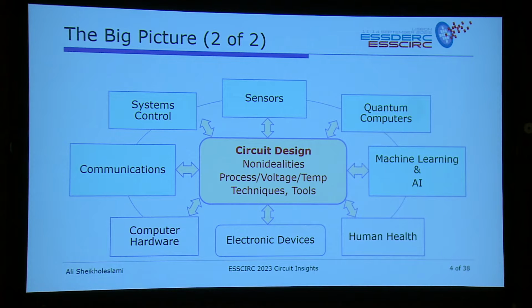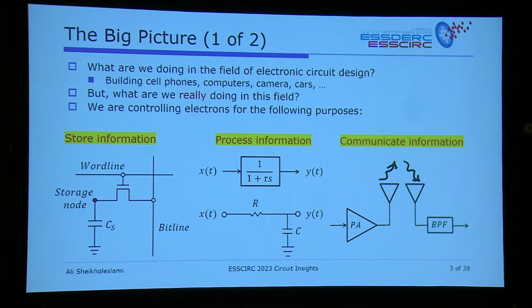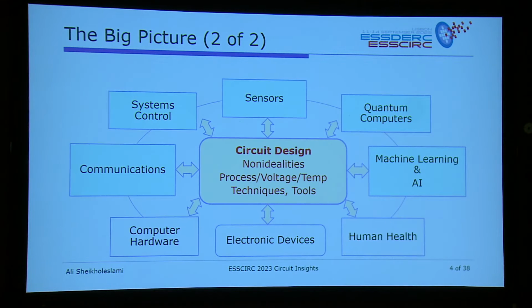Now, as I will mention to you briefly, and you'll see it through the team today, dealing with one circuit, one element is easy. You can just write the equations, you can get it to work, and it's all good. It's only when you get many of them, thousands of transistors, that you get the situation where these transistors have their own individual characteristics. We intend them to be identical, but there is a random process involved. And then how do you make sure that at the end of the day, when you make tens of thousands of these transistors, they will do what you want them to do, that they follow the same equation that you had in your mind?